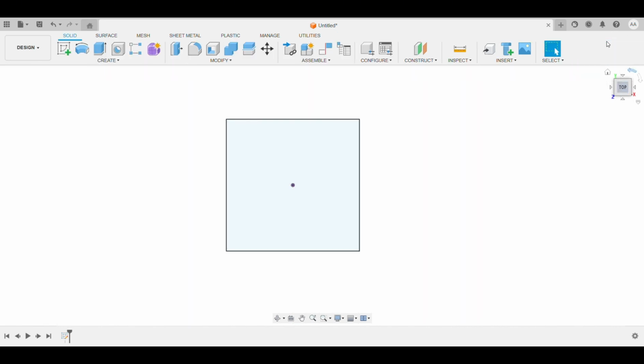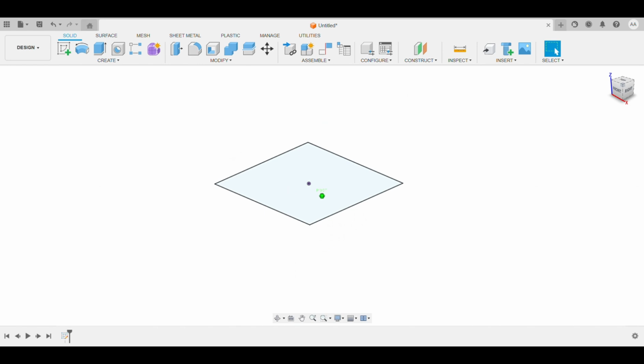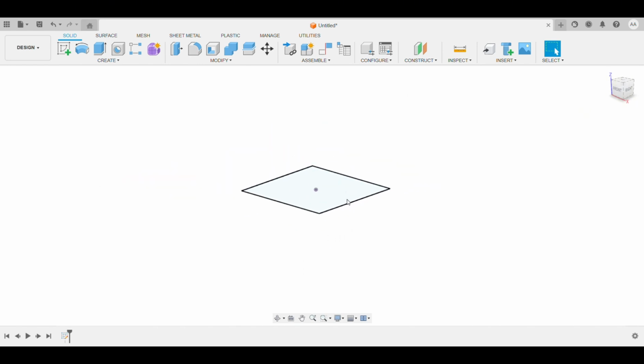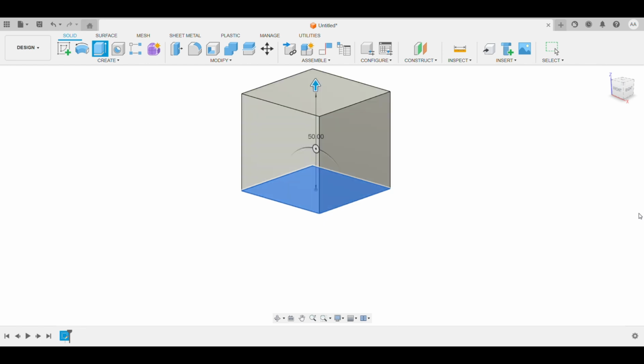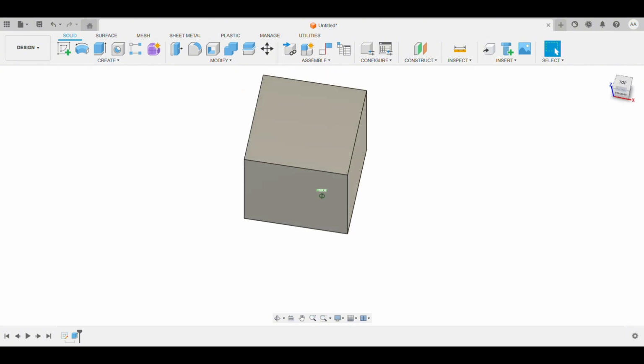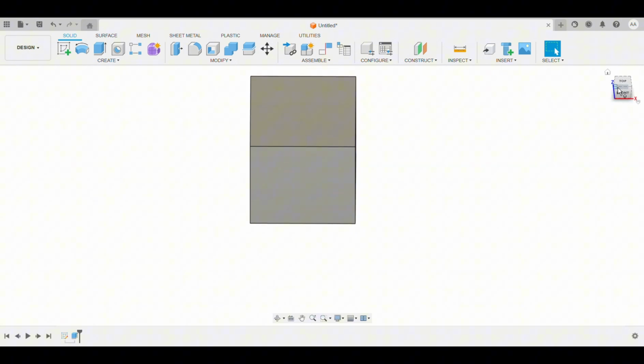And then we're going to hit complete. So now we have completed this sketch. So we have a simple square here. Now this is still not a 3D shape. So now that we have the basic shape, we can hit extrude. It's already automatically selected this, but basically you can select your sketches. This is the only sketch we have. Select this and then type in our 50.8. And now we have our cube. So not too difficult, but it is a little bit less intuitive than TinkerCad.